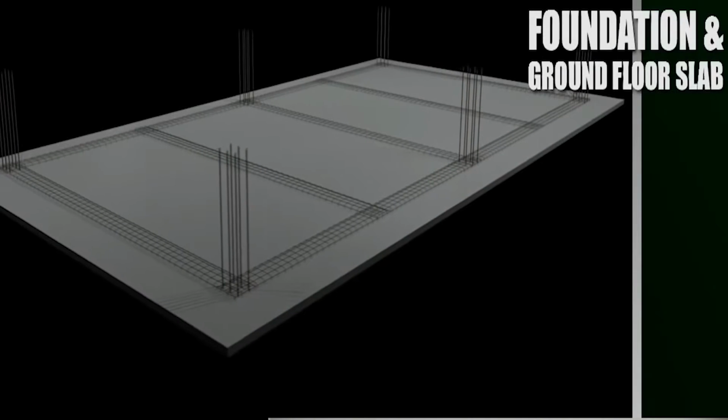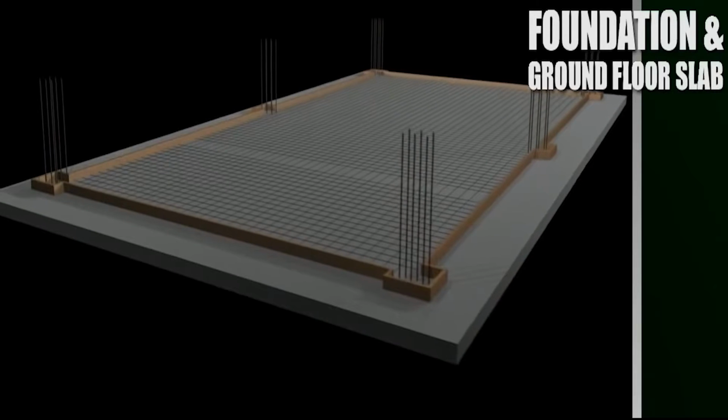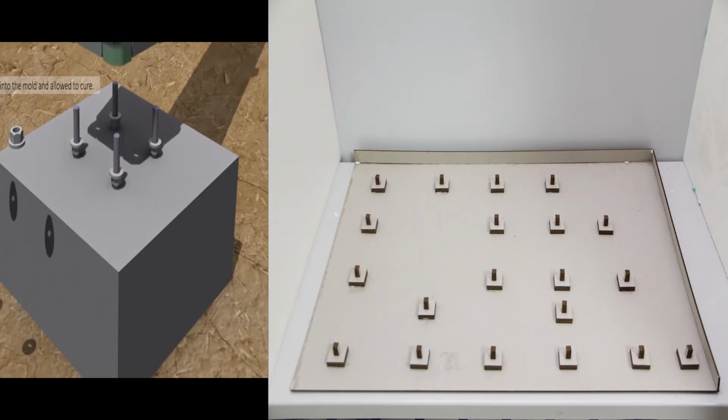The land has been cleared and the ground is broken. Generally, excavation is carried out for the construction of the foundations, including digging holes and leveling. The foundation is built cast in situ with the welded ribcage as reinforcement. The footing is embedded within 1 meter deep into soil, supporting the structure above by connecting the stump to the column.